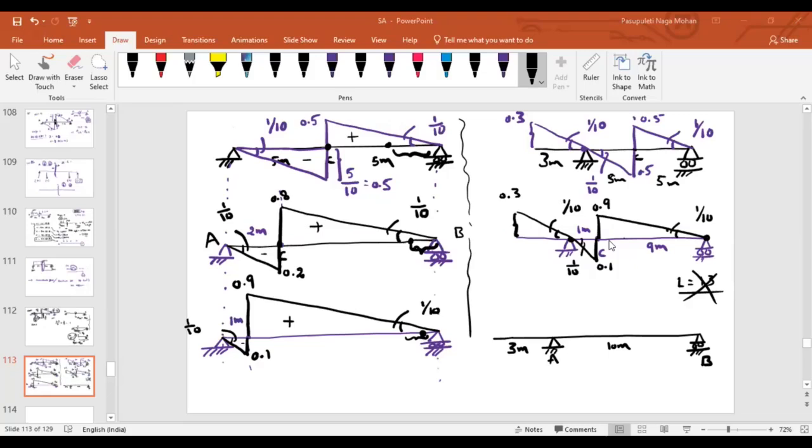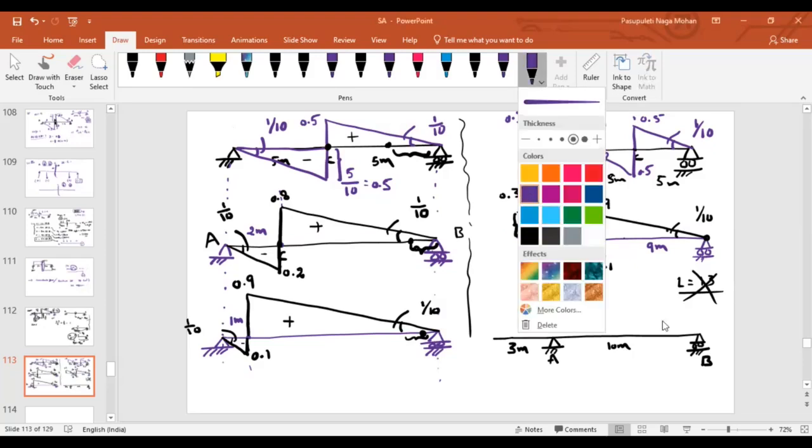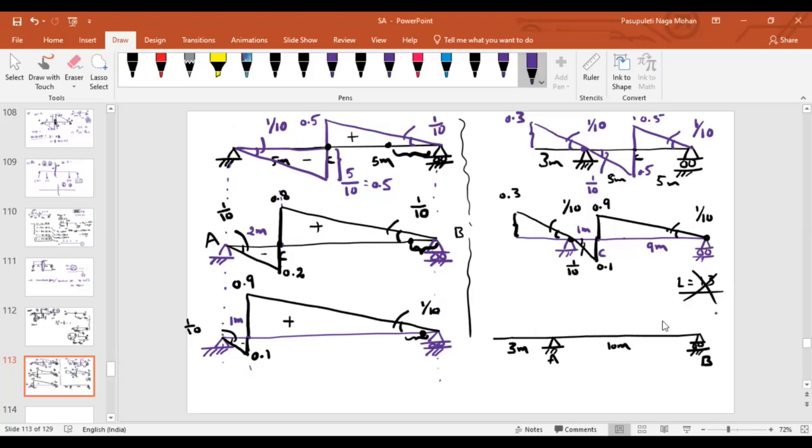Wherever there is an abrupt change in the shear force diagram, at that point we cannot define the shear force. Or blindly I'm saying, wherever there is a concentrated force or reactions, we cannot define the shear force. Similarly, as at point A reaction forces will develop, we cannot draw ILD for shear force exactly at point A. So instead, we will say just to the right of point A.